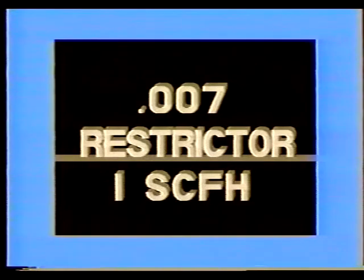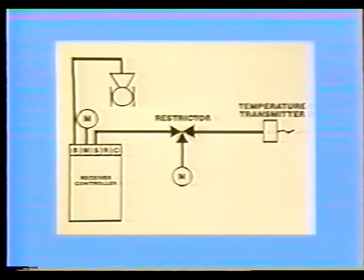This will provide a flow of 1 SCFH, or standard cubic foot per hour, of air through the restrictor. This flow or volume of air is provided to the branch line as the source for the branch line signal, which is then regulated by the operation of the transmitter.